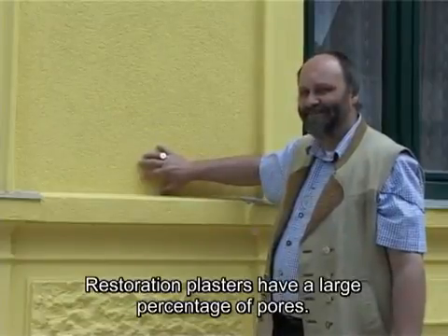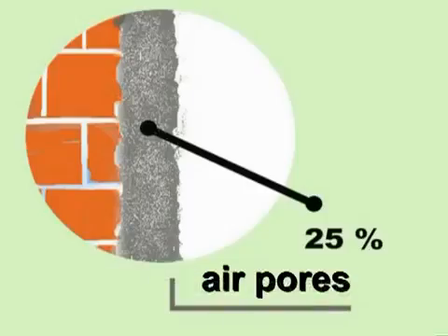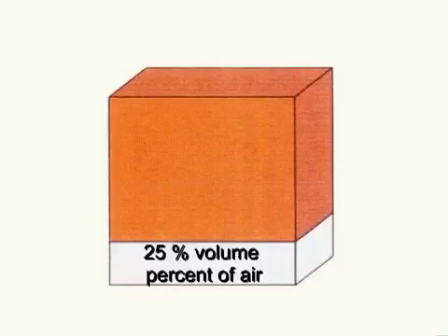Restoration plasters have a large percentage of pores. About 25% of the plaster volume must be air. Air pores provide the plaster with better thermal insulation properties than conventional plasters.